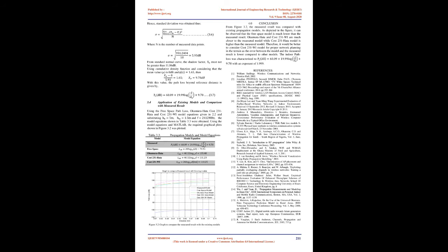The Hata model specifies the base station antenna height to be from 30 m and the mobile station height from 3 m, with room for correction factors. Equation 17. Okumura-Hata path loss model equations for different terrains are given. 2.2.4 Walfisch-Ikegami path loss model. COST 231 WI is a semi-empirical path loss model that takes the characteristics of the city structure under study into account. Such characteristics include heights of buildings, roof, widths of roads, W, building separation, B, and road orientation with respect to the direct radio path, F.